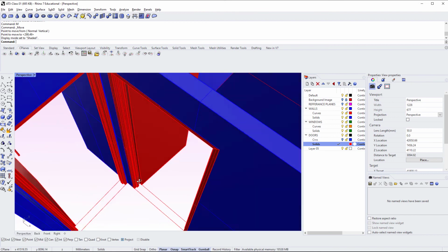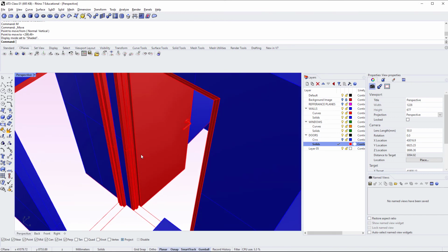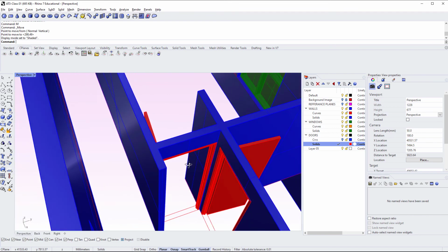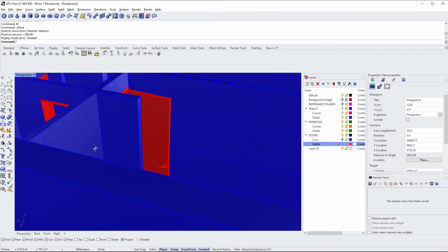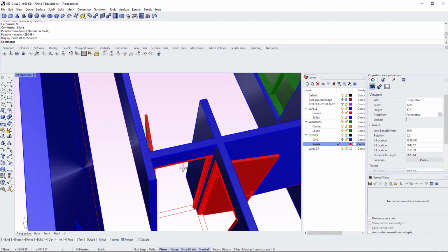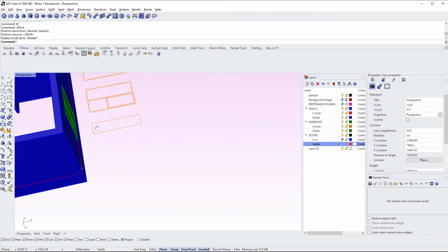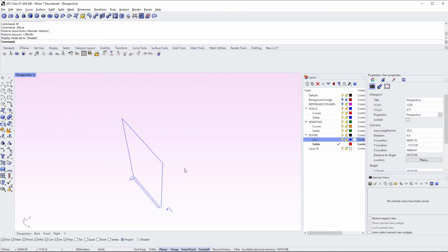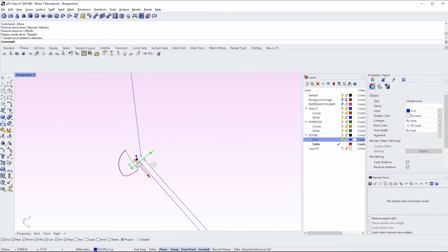We now have doors with our door jambs, with door handles that are open into each of these rooms. And that is more than enough to show design intent. Now, if you want to change the frame type, that is as simple, I'll turn back on the curves. So here's our curves over here. That is as simple as just changing the profile